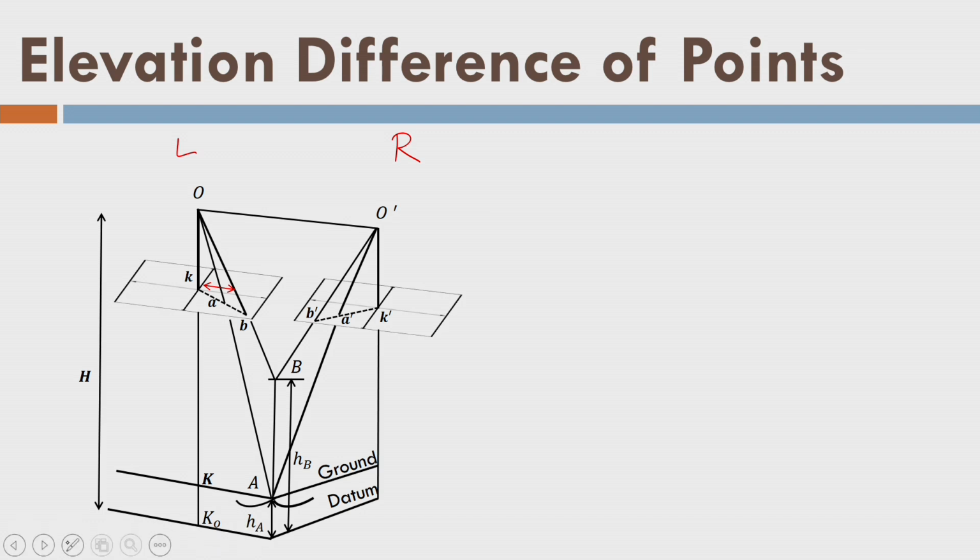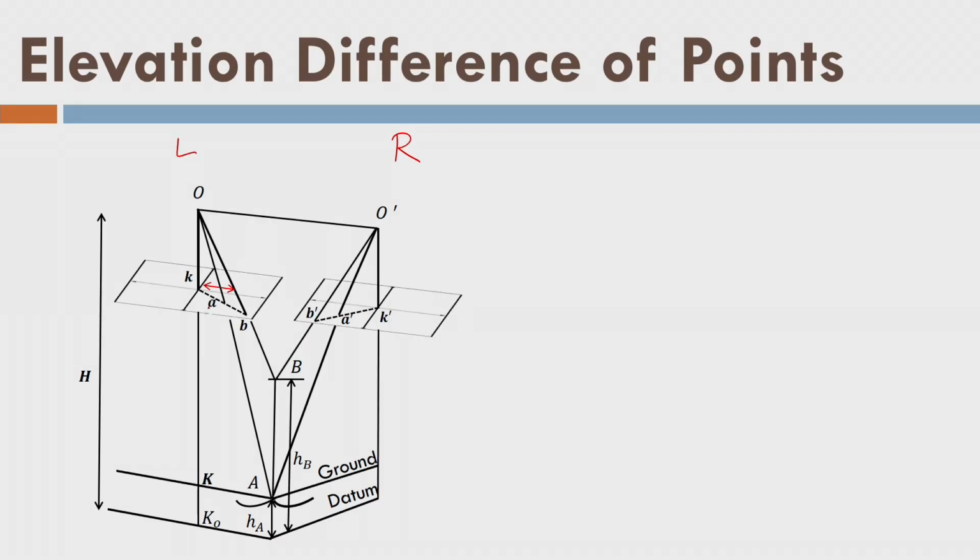You can see that point A or point B, because of the height difference, let us say that it is a building and the building height is represented by A and B. So, I can see what is the change of the location A. A has come to B because of the relief displacement of the point at A, because it has a height HB minus HA. These are very intermixed, very nice concepts we derived about the relief displacement in the last lecture.